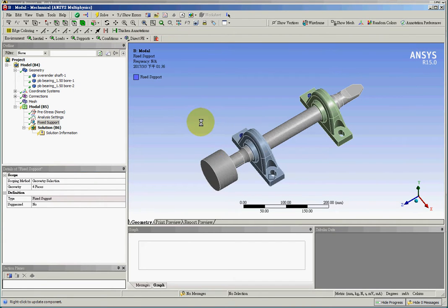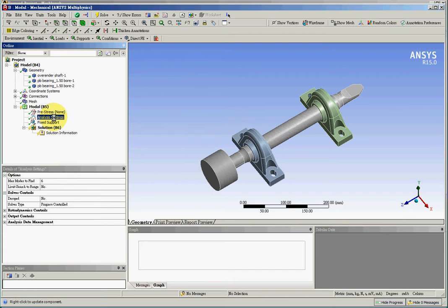And also again, you don't place any load on it because it is blanked out. So again, ANSYS is a more rigorous or robust software. It prevents you from making mistakes by blanking out the external load part. So before we run the solution phase, we will have to change these numbers, and I'll calculate 6 different mode shapes and frequencies. So I leave it as 6.